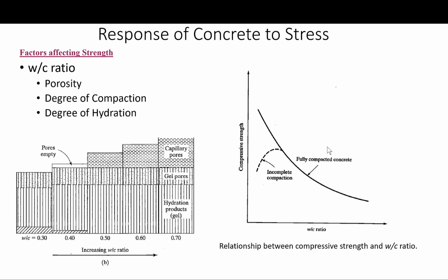So even though the strength of concrete is dependent largely on the capillary porosity or the gel space ratio of the paste, if you remember, these are not really easy quantities to measure or predict. So they are therefore not suitable for use in the mix design procedures outlined in the previous module. Fortunately for us, the capillary porosity of a properly compacted concrete at any degree of hydration is determined by the water cement ratio, if you remember.